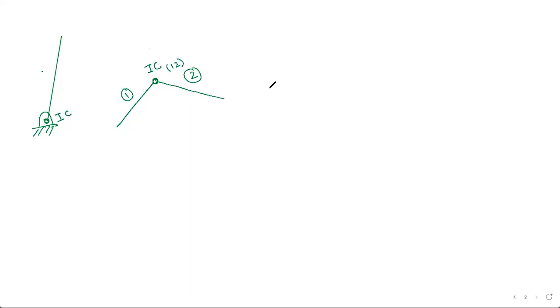And next, if there are higher pairs, if you see that a roller is rolling on a floor, it's a point contact. So the instantaneous center will be the point of contact. So this is your instantaneous center of rotation, IC. So this is your IC here, this is your IC here. Let's take 1 and 2. So 1, 2, IC. So here also 1 and 2. So I can say 1, 2 with respect to 1, 2 is in pure rotation at that particular moment.